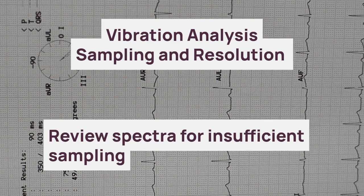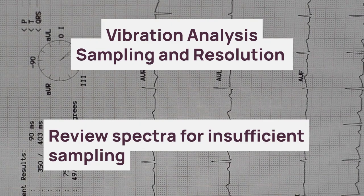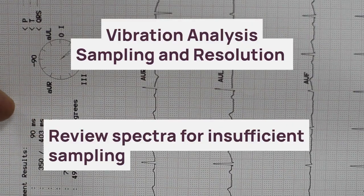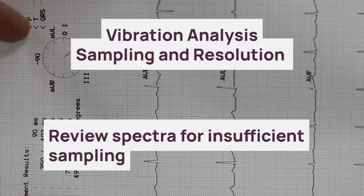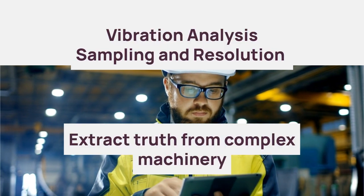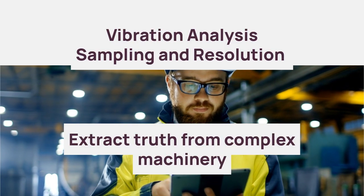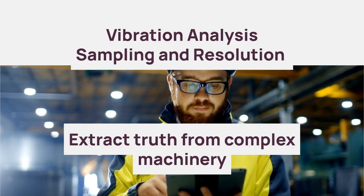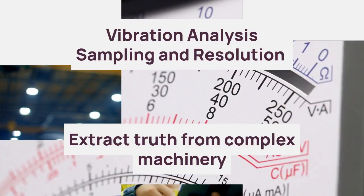Practice using your tools and review spectra for signs of insufficient sampling or low resolution, such as unexpected peaks, blurred features, or missing patterns. A deep comprehension of sampling and resolution empowers you to extract truth from complex machinery, detect faults earlier, and protect your operations from unexpected failures.